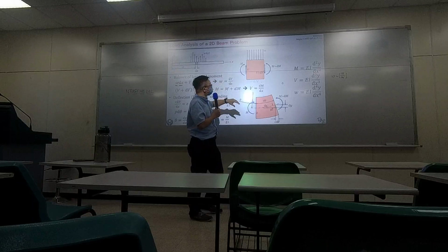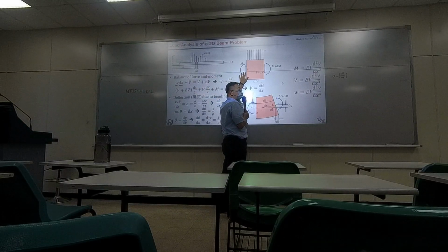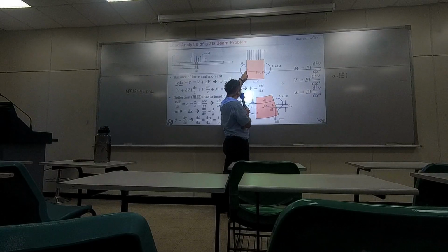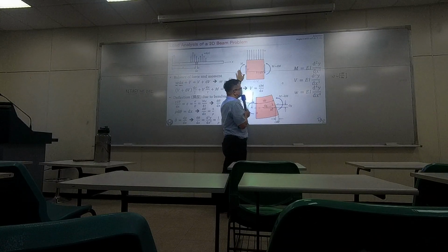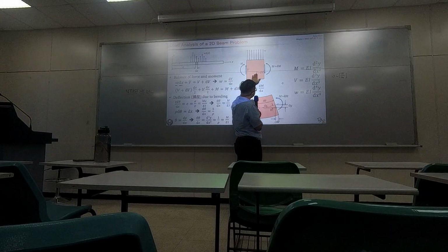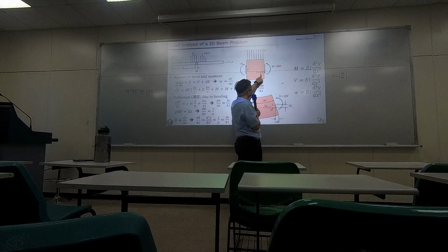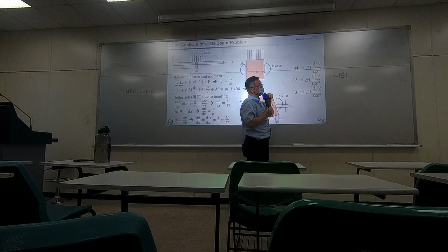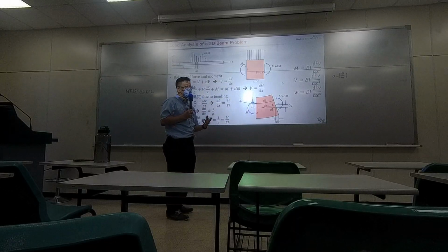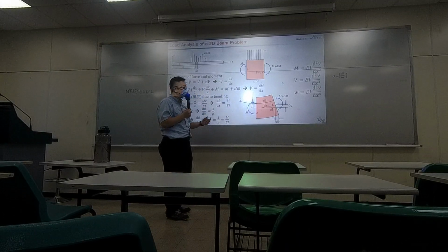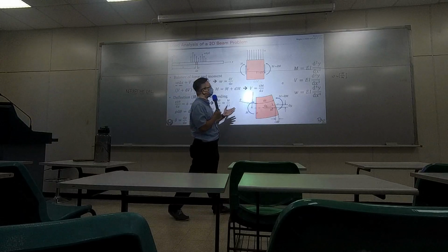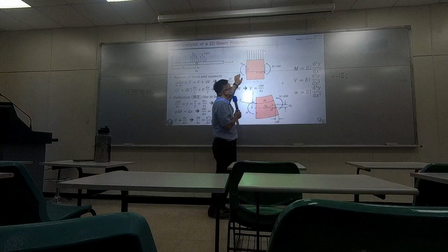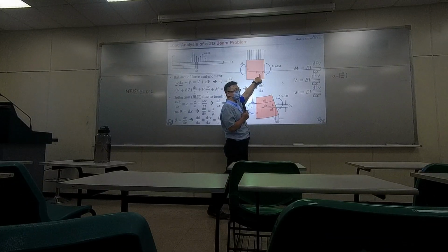Let's assume we treat the left-hand side as having the shear force V and moment M. And on the right-hand side we have shear force V and M as well, but there could be an increment of the shear and the moment, so dV and dM. The issue is whether it is actually increasing or decreasing, so you need some math to figure that out. But in the current math symbols and certain definition of the symbols, we treat them as positive increments.